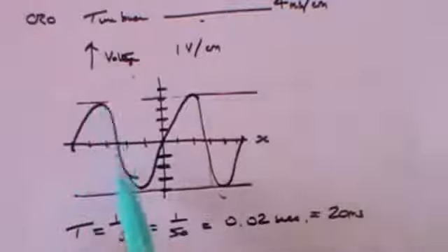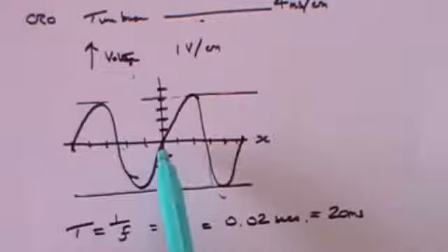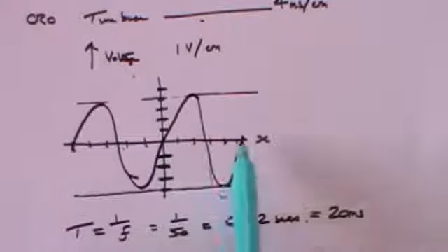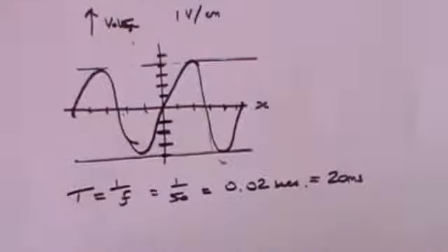So I've drawn the complete wave to occupy 5 centimetre divisions, and I've tried to do the same thing here, although it looks a little bit odd. So that's the shape that we will get on the cathode ray oscilloscope, which is what we were asked. That for AC.